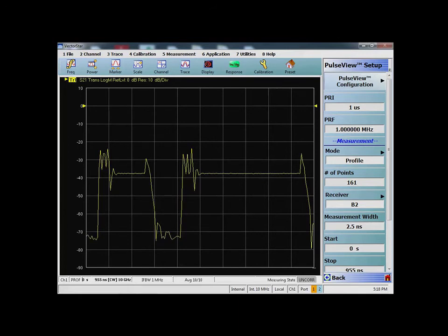In this particular demonstration, where we are using the pulse demonstration module, the A1 receiver is still getting a CW, because it's easier. But if you need to have the pulse modulator test set in place to give you RF pulsing, or say DC or IV pulsing, you can still use the pulse modulator test set, which I will show you in my next video.